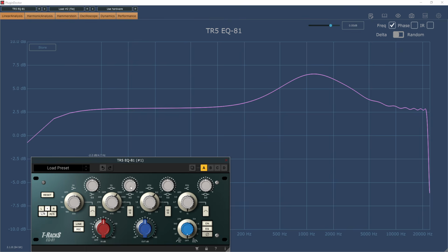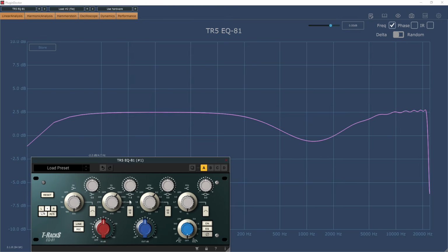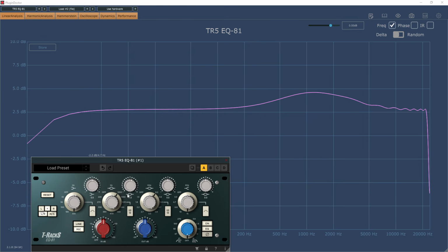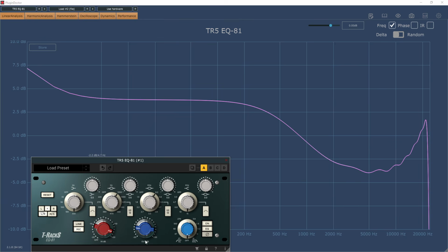You can test an analog modelled EQ and get proper results, so long as the test signal doesn't get too hot. But as soon as you introduce any significant extra harmonics, the results cease to mean anything at all, and we're no longer getting any useful information. I see this mistake over and again in YouTube videos, and this information really needs to be out there. You can't measure a nonlinearity with a test called linear analysis. Would it help if I explained how this test probably works under the hood?